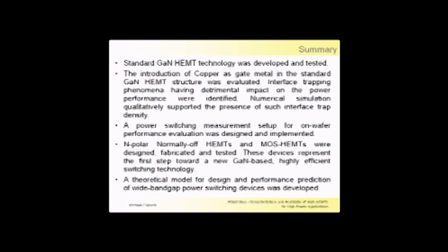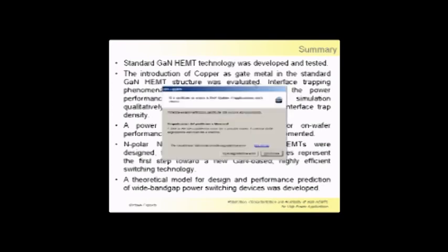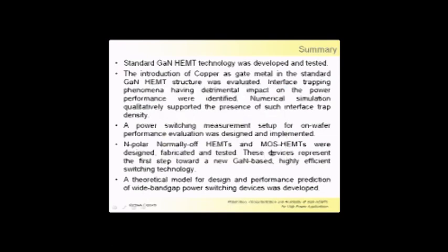So we successfully introduced a normally-off gallium nitride HEMT, and we studied MOS structure for gate current suppression. And then we developed a complete theoretical model that gives us all the tools that can help us to design and implement an efficient power switching transistor.